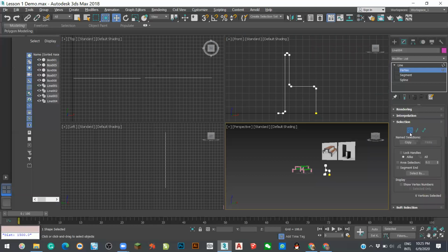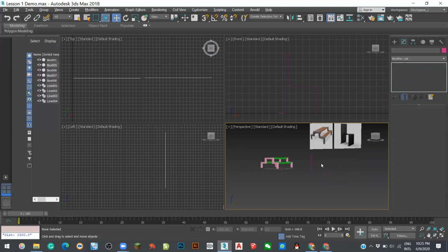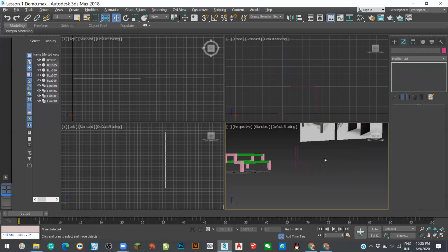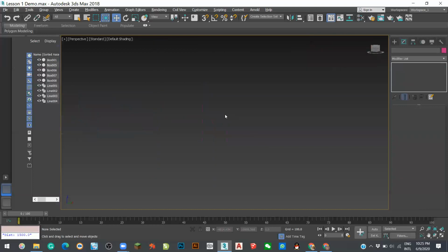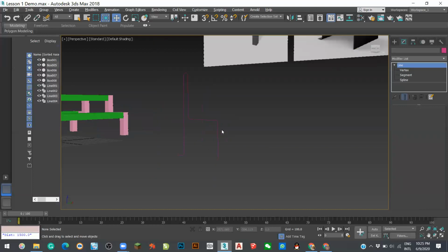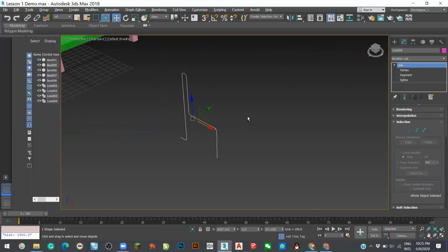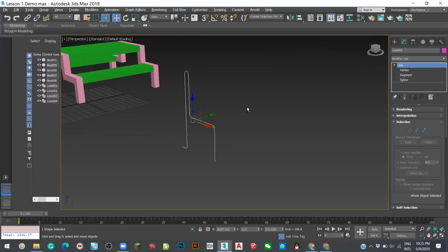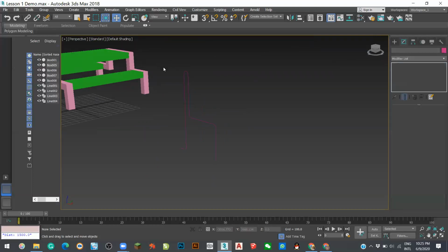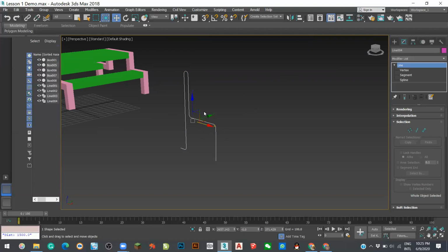After that, you need to unclick this one to exit the command. Then I will use this one. So I click this viewport, Alt W. Select Alt and middle mouse button. I oblique the view.